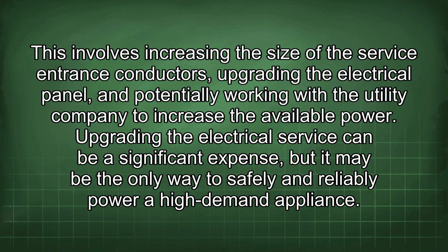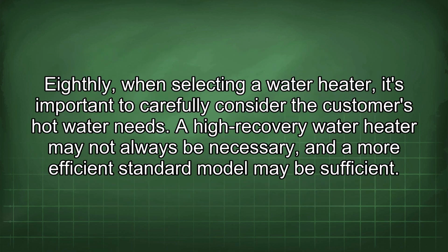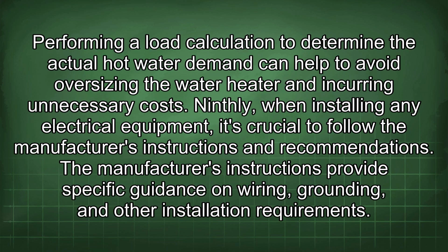Eighthly, when selecting a water heater, it's important to carefully consider the customer's hot water needs. A high-recovery water heater may not always be necessary, and a more efficient standard model may be sufficient. Performing a load calculation to determine the actual hot water demand can help to avoid oversizing the water heater and incurring unnecessary costs.